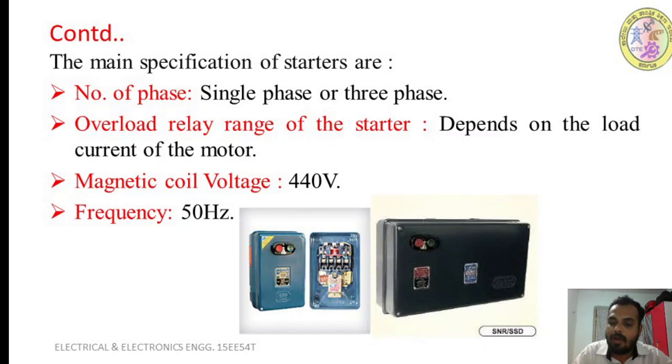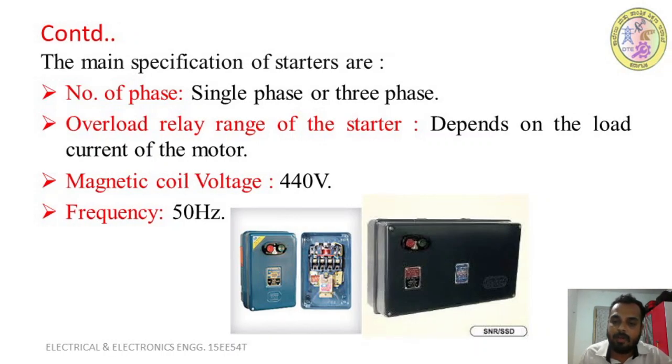So we have used. And next we have seen MCB, that is miniature circuit breaker. This is also very important, and the rating of the MCB depends on the load current, right? So next ELCB we have seen. The rating of the ELCB also depends on the load current and the current sensitivity of the load current, right? So this is about ELCB.